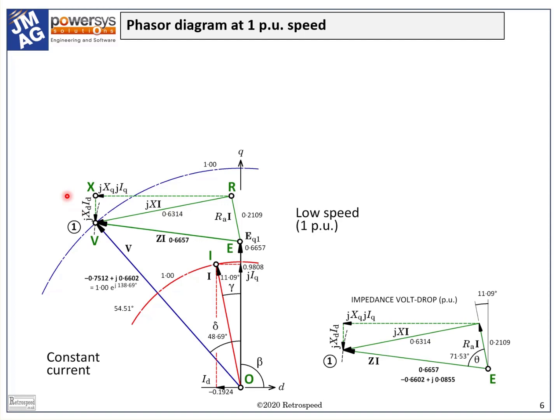Moreover, the resolution of the reactive voltage drop into separate d and q axis components helps with the control theory and with the dialogue between the motor designer and the control engineer. This is extremely important. Before we consider another operating point, let's take note of the power factor. That is the fundamental power factor. This is important because it's a measure of the electrical power relative to the volt-amperes provided by the inverter. So it tells us something about the required size of the inverter. The cost of the inverter is significant, and it's obviously related to its volt-ampere capacity.